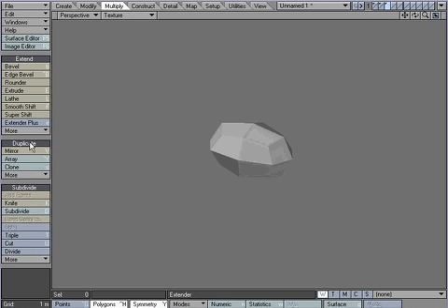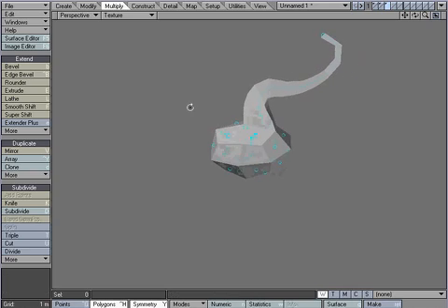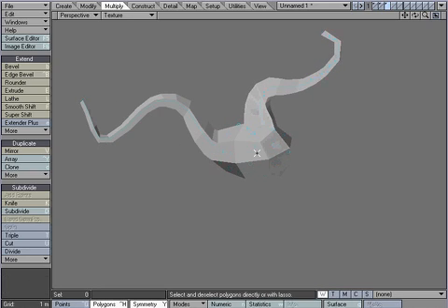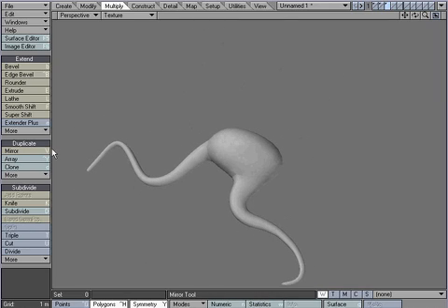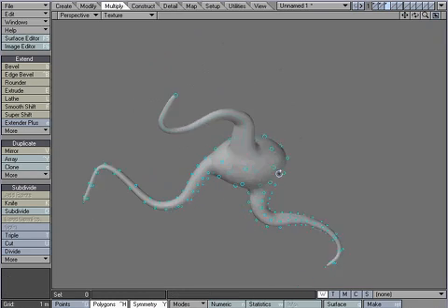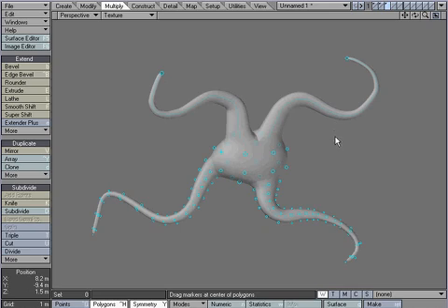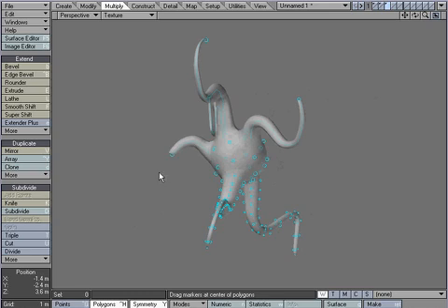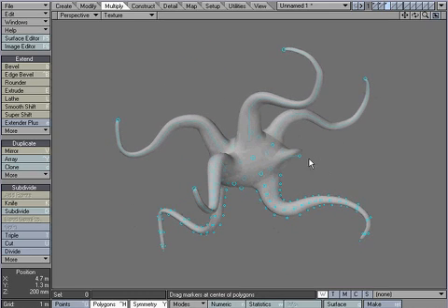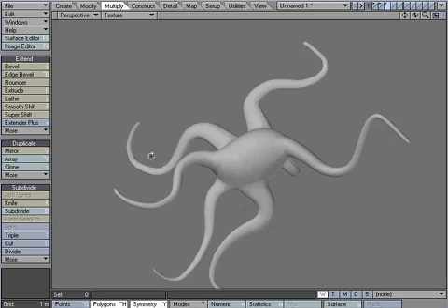And I'm going to go over to Multiply, and under the Extend More, I'm going to use Magic Bevel. It puts these little handles on each one of my polygons that I can just click and drag out. Now, if I hit the Tab key, of course we're back in subpatch mode. And let's go back to Magic Bevel, and I'm going to pull that out. And see, I can work in polygonal or subpatch mode in this. Right? This is a great way for doing hair or for doing tree trunks, any kind of vines, anything like that. It's a fast way to work.